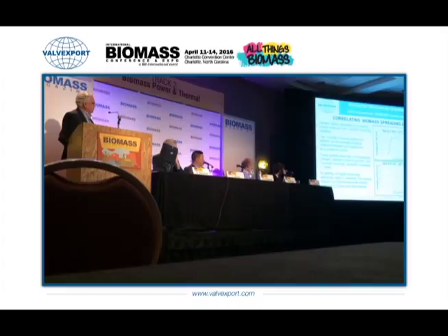Between these two graphs, a change between 2 and 4 inches in water column, nominal, meaning between two highest points, you get 1 meter or 3 feet longer throw than you did before. And that kind of correlation done for any biomass with any moisture allows us to do the programs to then assure that you can do it in any grate.